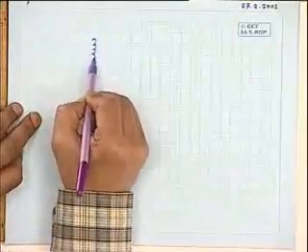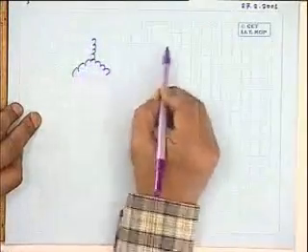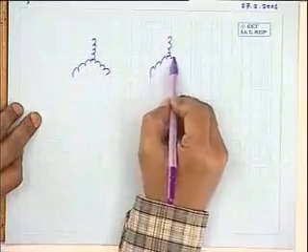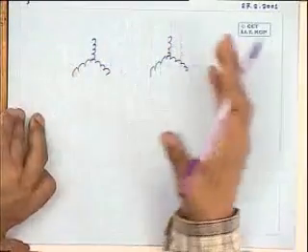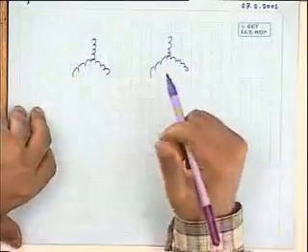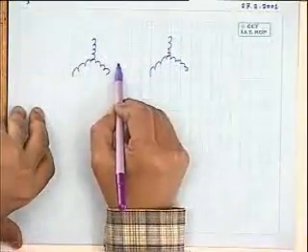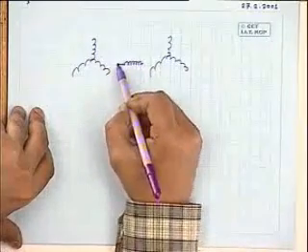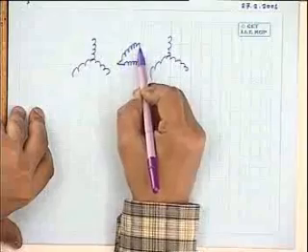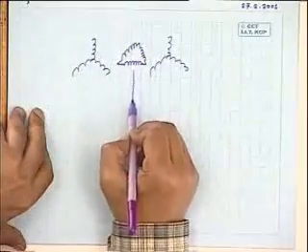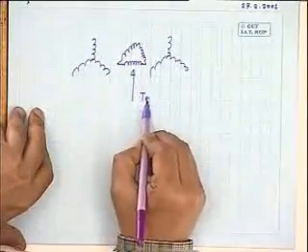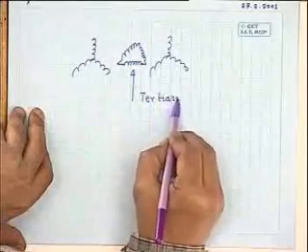So sometimes what is done is this, that in a star-star connected transformer, which is to be used as star-star connected out of some compulsion, that is the level of voltage of the primary and secondary both are high and you have to use star-star connected transformer. Then in that transformer there will be additional windings provided on the secondary side which will be kept connected in delta fashion, and such a winding is called tertiary or stabilizing winding.